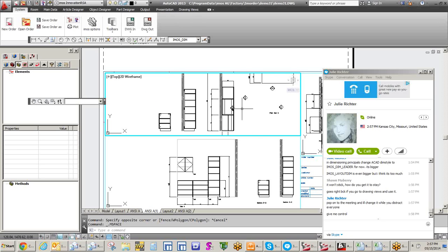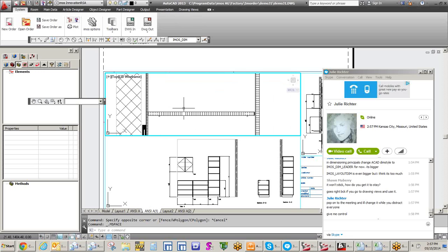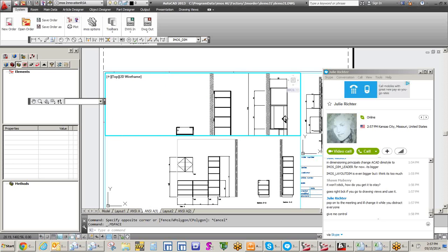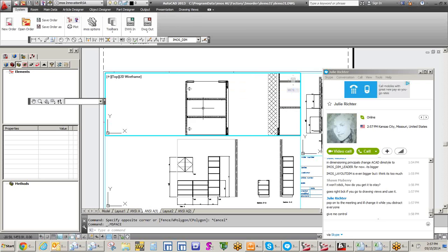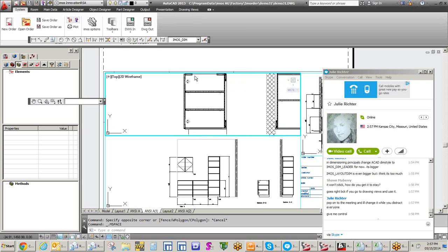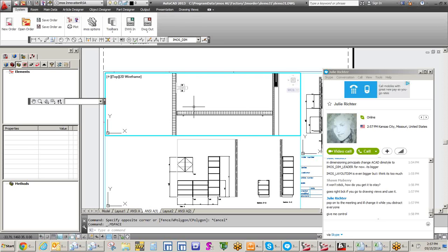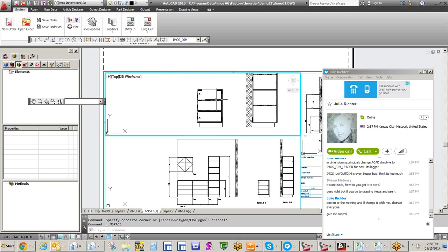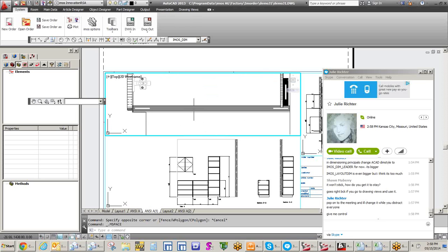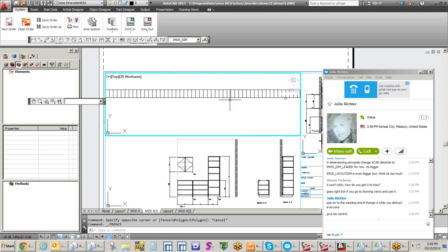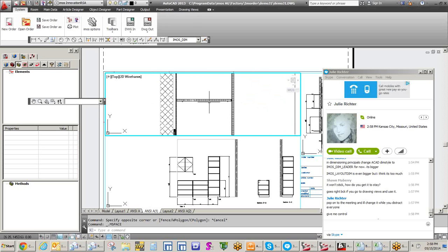Yeah. And Sean, I want you to zoom in real close to a section. Notice the edge. Go to the base section. I noticed that it was showing edge banding the other day when you were talking, Sean. The edge banding, and it also shows the material if you ask it to. It types the material into the, oh, your text is white, that's why. Oh, it tells you the material? Yes, it does. See that little white band area? It actually types out what material you're using, the material code.